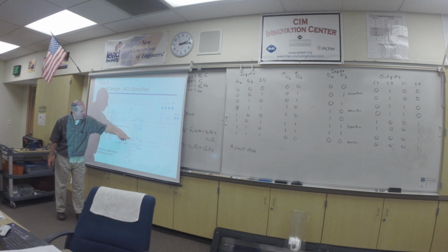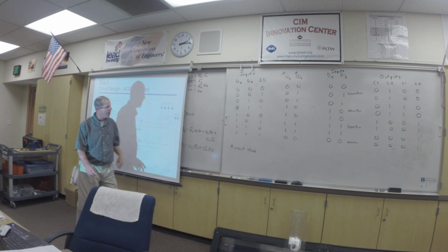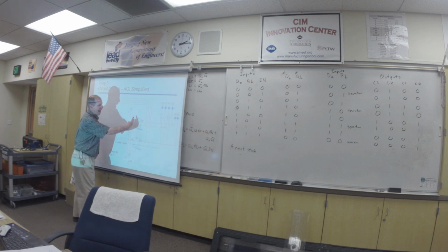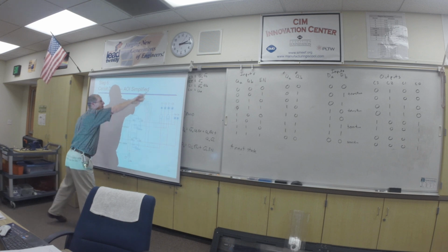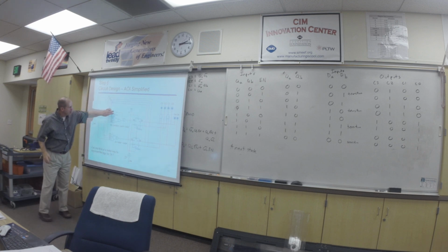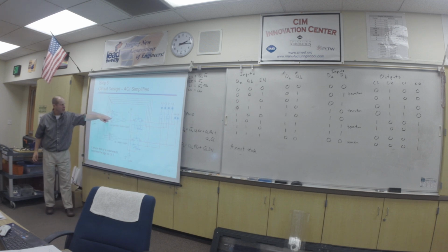The inputs into DA and DB, we just wrote the Boolean expression for those over here. So DA and DB come around here, QB and QB not come around here, and they become the inputs to DA and DB by just using some AND gates and OR gates. And these are actually labeled QA not, enable, QB.